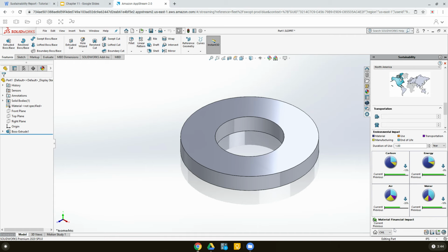So next, what I'm going to do is, this is our first trial, right? This is the first trial just to analyze the current design and set inputs. Now that we know this, we can set this as our new baseline. So at the bottom here, we have the set baseline option. You can click on that. So that becomes the new baseline, right? That gives us the opportunity to change a few things and hopefully reduce carbon footprint, air acidification, energy consumption, and water eutrophication values.